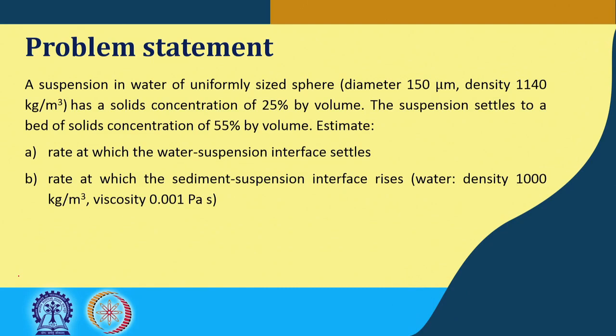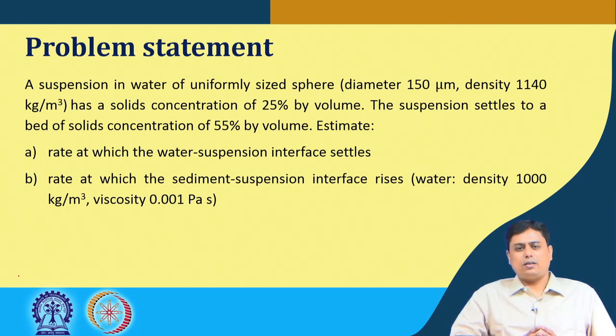So we have to calculate the rate at which the water suspension interface settles. So there is this water and suspension interface, and also after a certain period we have a sedimentation and suspension interface that would rise, considering the water density of 1000 kg per meter cube and viscosity 0.001 Pascal second.